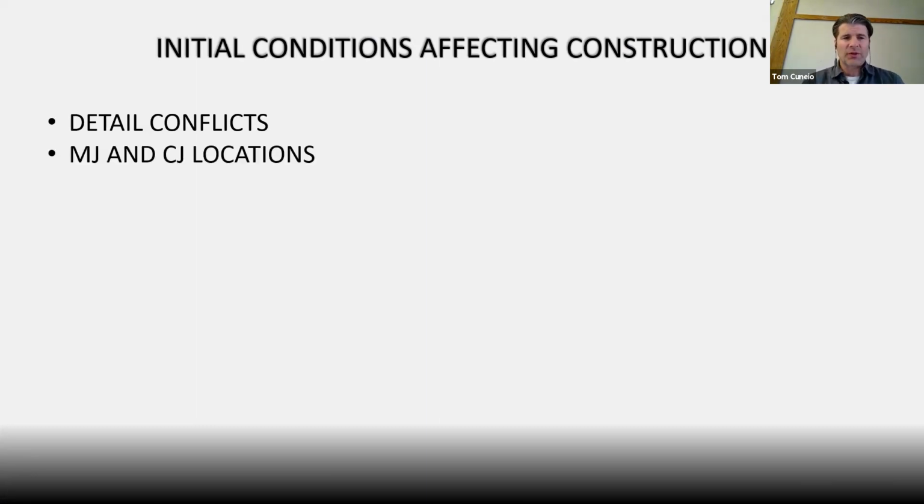Movement joints and control joints. These are elements in masonry designs that control cracking. They are very often neglected in the design package, so we're trying to tackle those things right on the verge of construction. Vertical rebar. This is the steel elements inside a masonry wall that give the structural tensile strength to masonry. They're very poorly understood in design, and we're exploring really what the design ought to look like as we build.